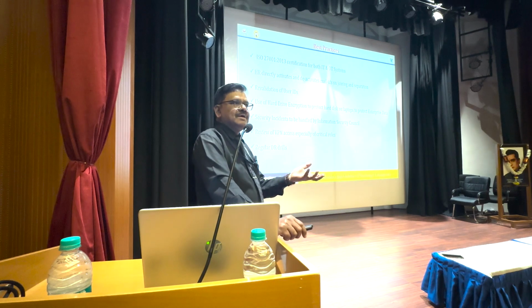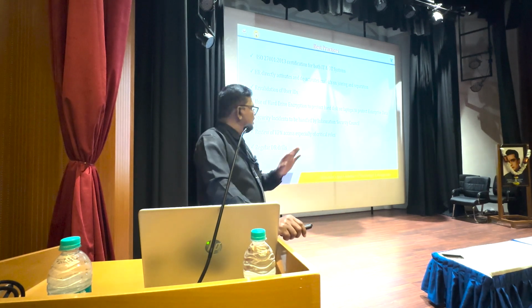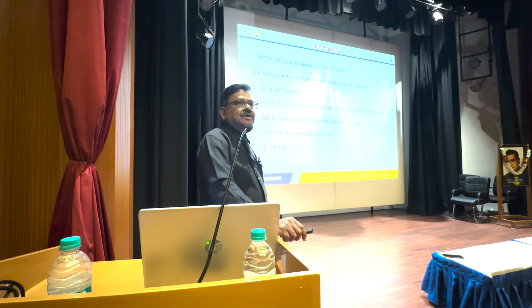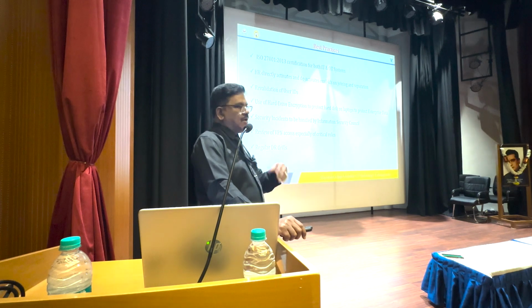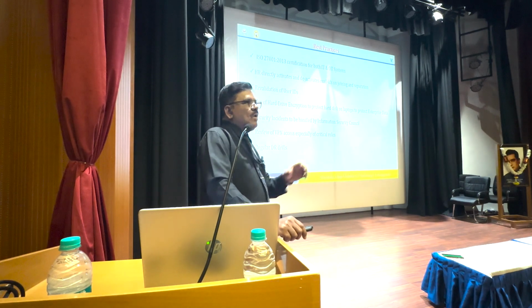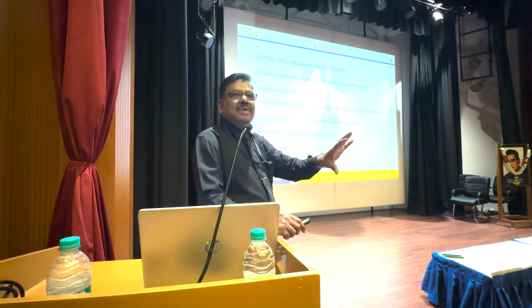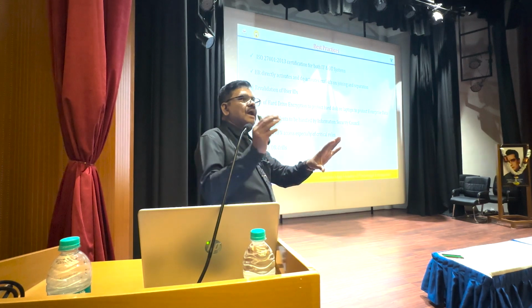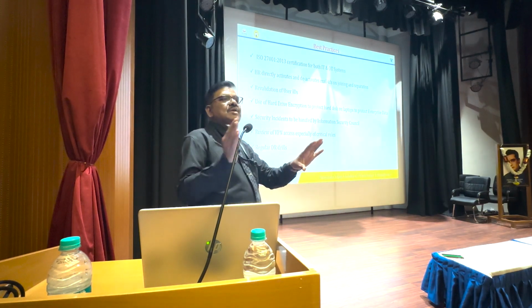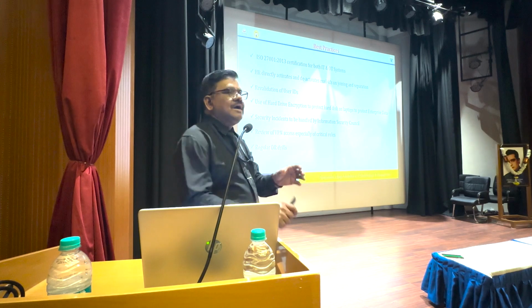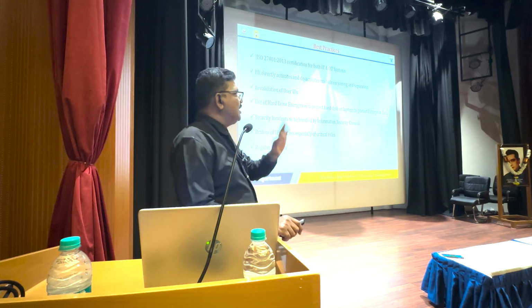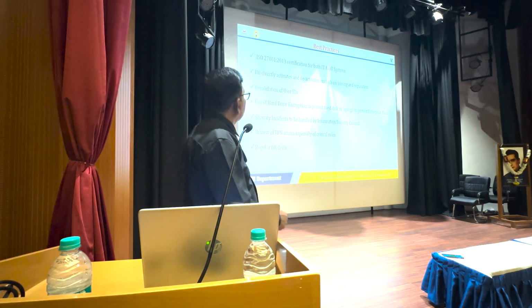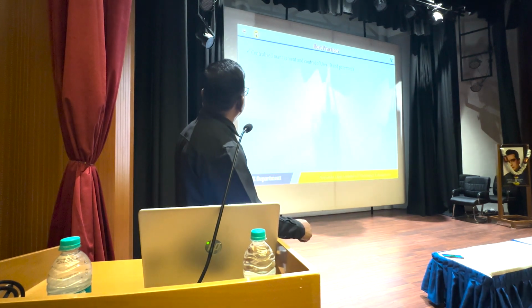However, this software may or may not stop the attackers. Then you have to use VAPT, vulnerability assessment and penetration testing, frequently. Then decoy. So what is decoy? One original PMU instrument will be there. Then you create 100 virtual PMUs, so that the attacker doesn't know which one is original. This is one way you can avoid cyber attacks on our system.